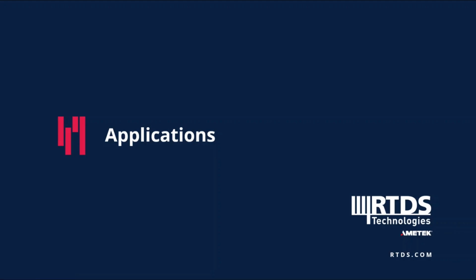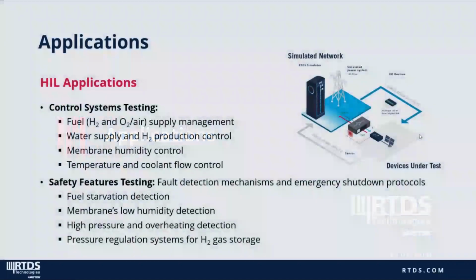Now let's have a look at application of the hydrogen simulation models. This slide highlights some key hardware-in-the-loop application of the new hydrogen multi-energy simulation facility. One major focus is testing control system of hydrogen systems. Using these models, we can test fuel supply controllers including hydrogen and oxygen delivery, ensuring proper flow and response under different conditions. We can also test water supply and hydrogen production controls, which are critical for electrolyzer and fuel cell operations.